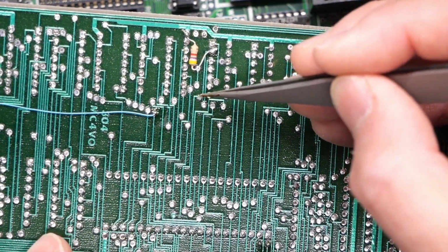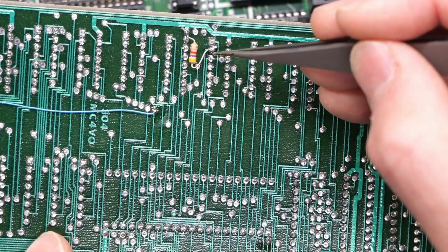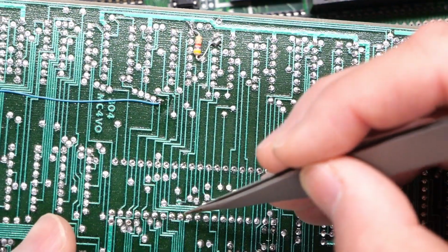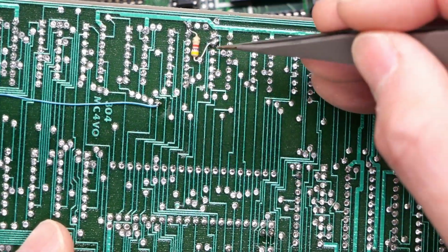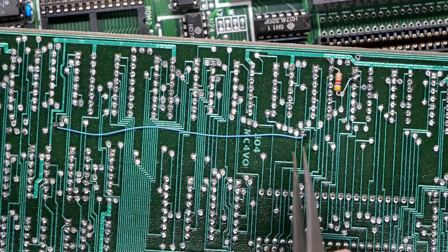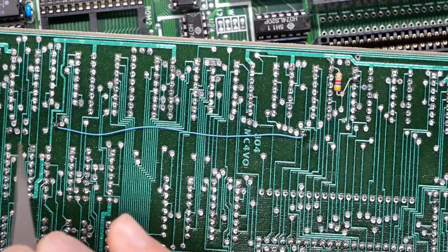Now you could try to put a little piece of metal across there to rebodge, or maybe even a blob of solder, or you just have to install a bodge wire from here to wherever this goes to, right there, that via, which I have in green. So put a wire from there to there, and that will restore the functionality. Ignore this bodge wire right here. That was just to fix the original mistake that I made with the mod, so you don't need to do that.